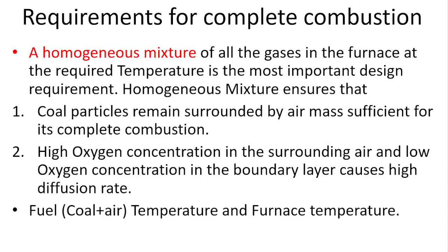The homogeneous mixture of all the gases in the furnace at the required temperature is the most important design requirement. A homogeneous mixture ensures that coal particles remain surrounded by an air mass sufficient for complete combustion. High oxygen concentration in the surrounding air and low oxygen concentration in the boundary layer cause a high diffusion rate. And then second, fuel, coal plus air, temperature, and the furnace temperature.